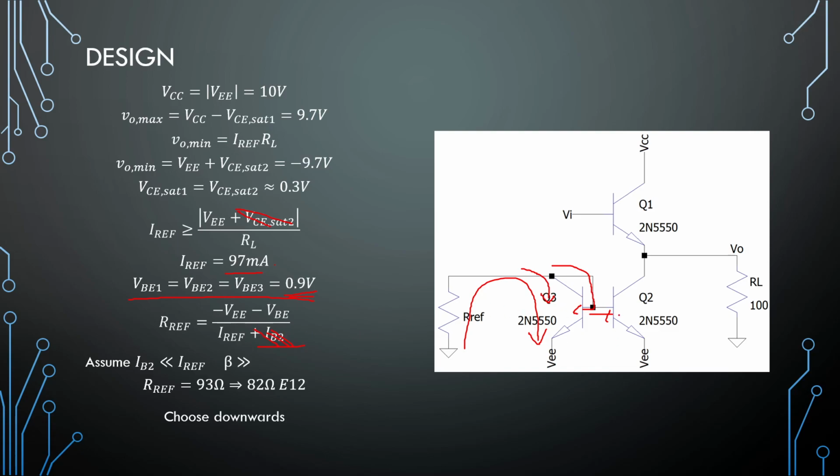So calculating the resistor on this side is basically applying Kirchhoff's. So first off, the VBE on this side and the VBE on that side will be the same. That's how the current is being mirrored. So if we assume this current flows through here and through this transistor and we ignore base currents, the collector current here is the same as the reference current flowing through the resistor.